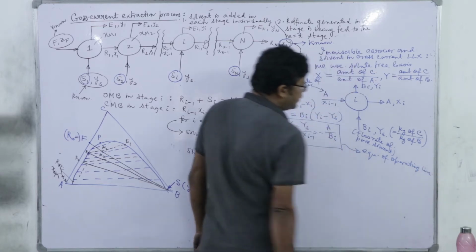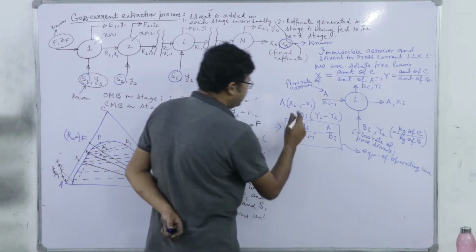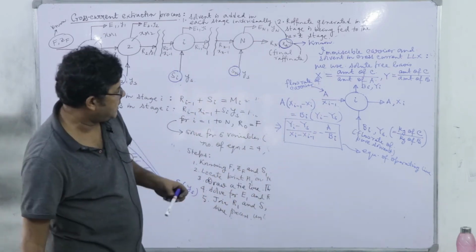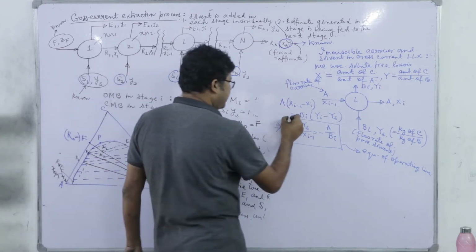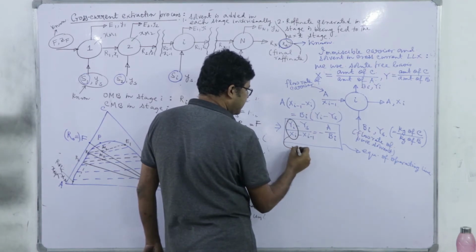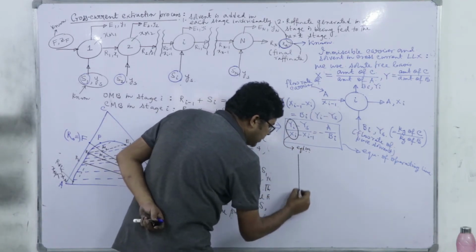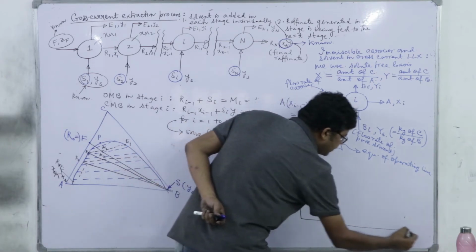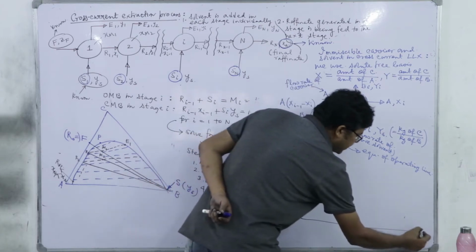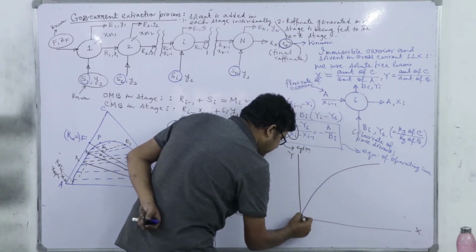Right? So how to determine the number of stages? Here, Y and X are in equilibrium. This Yi and Xi are in equilibrium. So how to determine the number of stages? We will draw the equilibrium data in the capital Y, capital X space, and let's say this is the equilibrium curve.